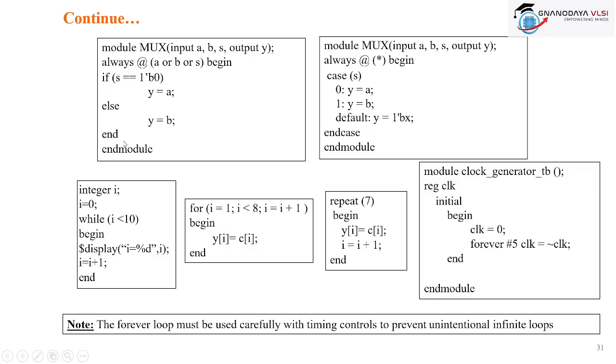Suppose for the mux, I told you, no. Module mux, input a, b, s, output y, always @(a or b or s) begin. If s == 1'b0, y = a, else y = b. You need to use the equality operator.